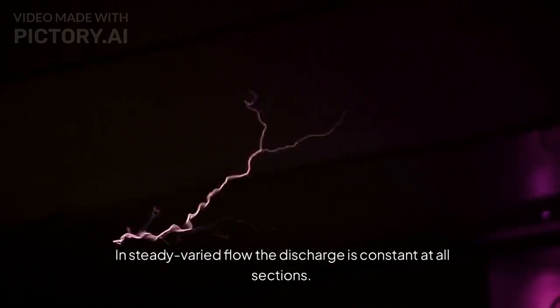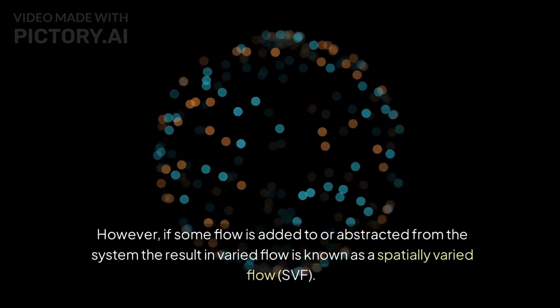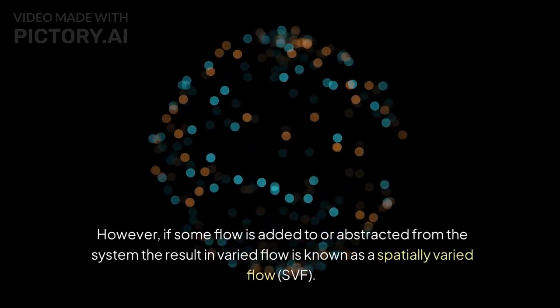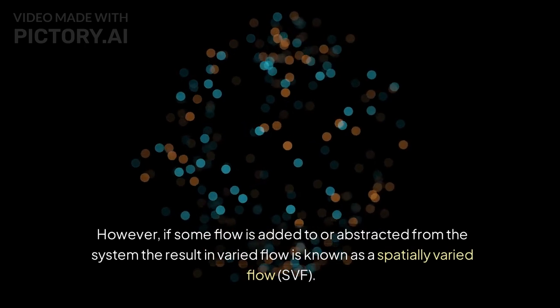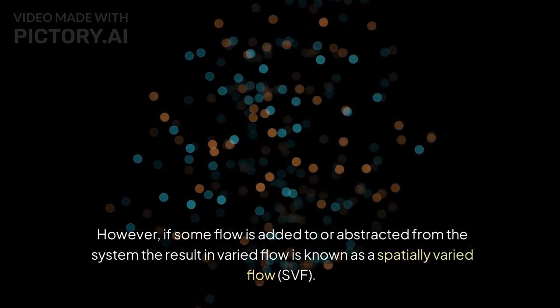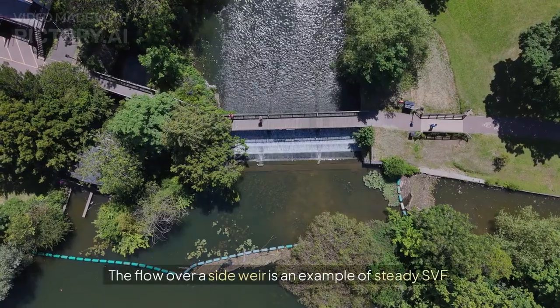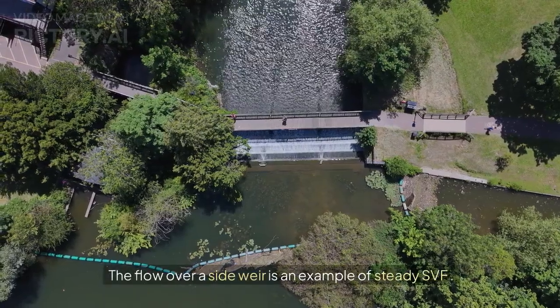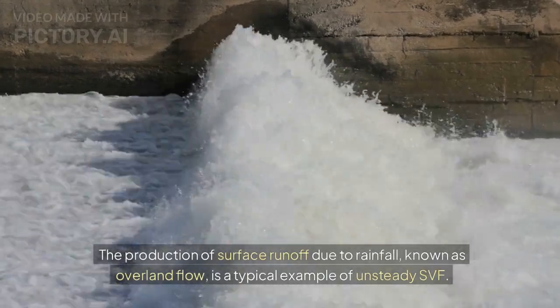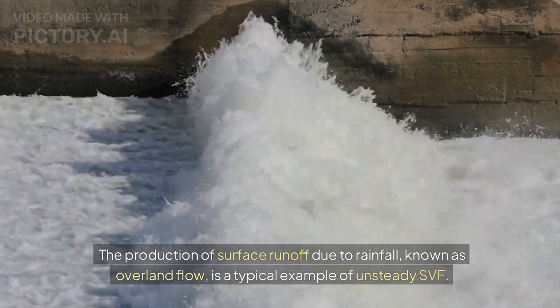In steady varied flow, the discharge is constant at all sections. However, if some flow is added to or abstracted from the system, the resulting varied flow is known as a spatially varied flow, SVF. SVF can be steady or unsteady. The flow over a side weir is an example of steady SVF. The production of surface runoff due to rainfall, known as overland flow, is a typical example of unsteady SVF.